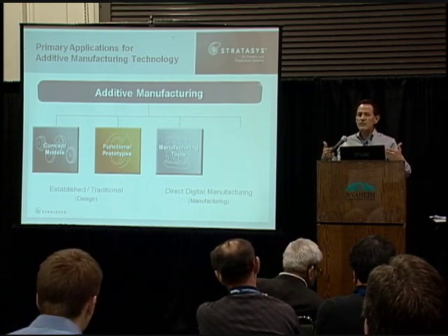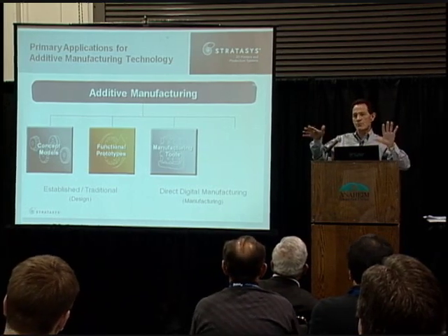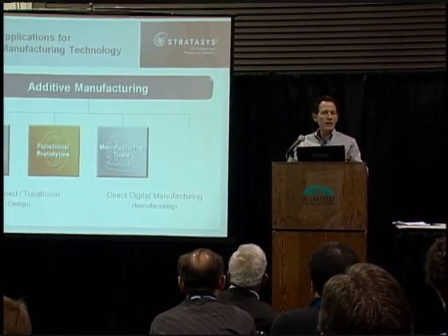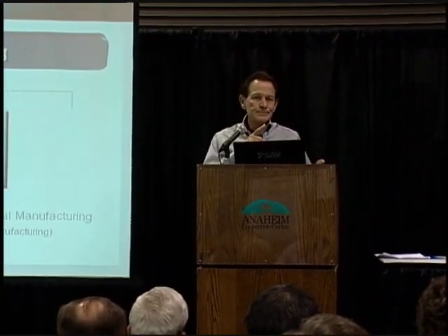A lot of our folks make drill guides, drill tools, especially in aerospace where you have erratic surfaces, things change, jigs, fixtures, assembly tools, quality control, CMM holds and fixtures and all of that. So manufacturing tools I put in that category. It's not the end-use part, but it's all those little gizmos and jigs and fixtures and gauges that you have to create to either make a part, assemble a part, inspect a part, even ship and package parts or move them around. So that's the manufacturing tools.